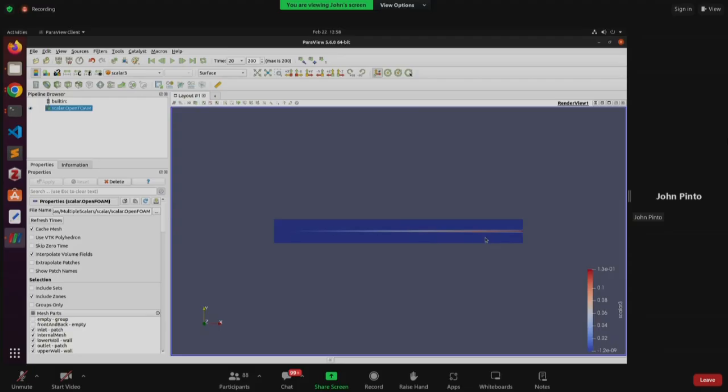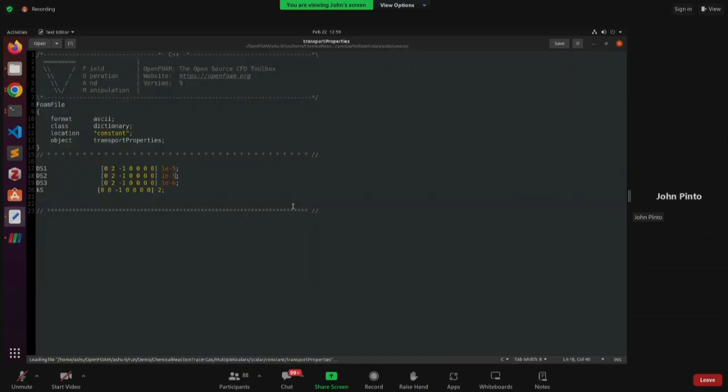You can increase the diffusivity further by maybe an order of magnitude, and you will see this red spreading more. Two things are coming in, they are reacting and creating products. So as the distance increases, the product's concentration will increase, so the phi value of the product will increase. This is what you're getting. You can run this by increasing your diffusivity value, maybe to something like 1e-4, and then see the results for yourself. So this is something that you can try.